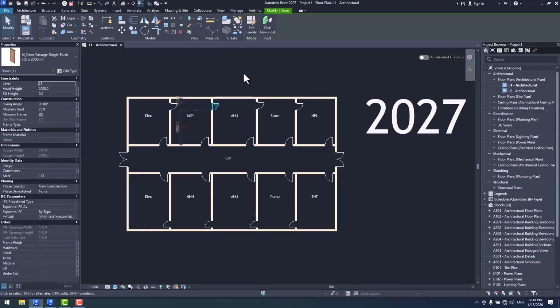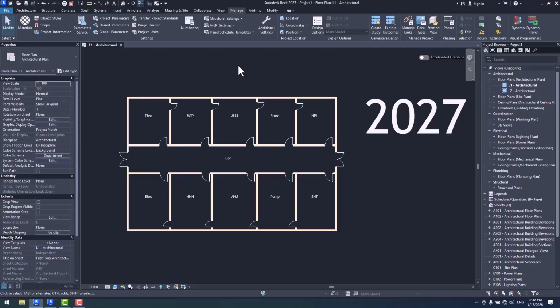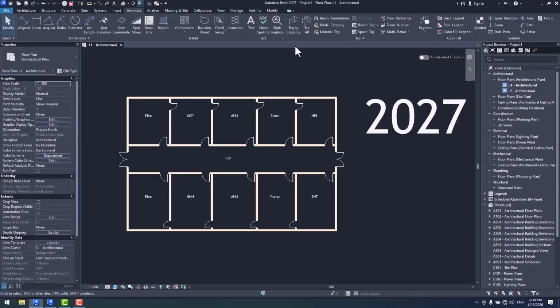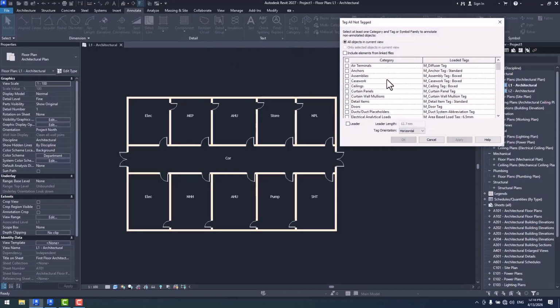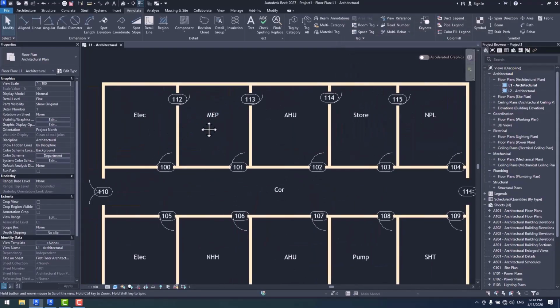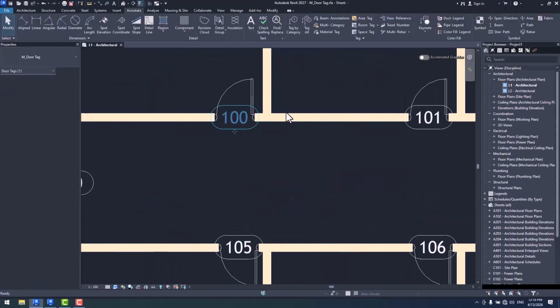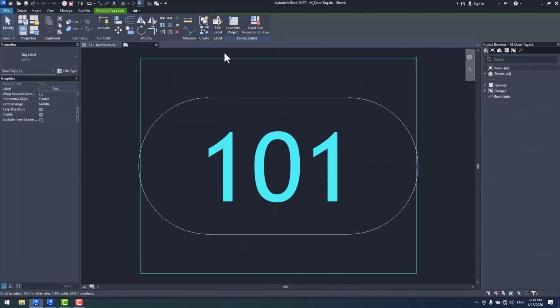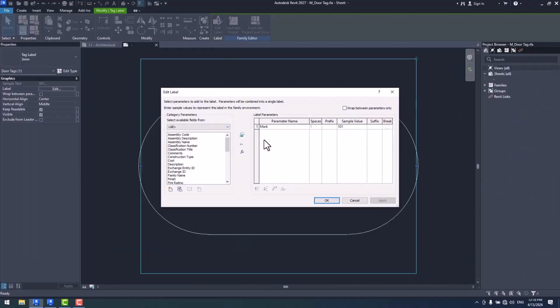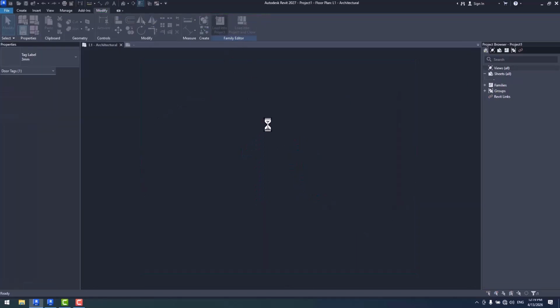First, let us set up some tags. Well, we can actually skip this. I mean, in that case, we would get the codes within mark, but I guess it's better to set up some tags first. So I'm going to use tag alt and set up these tags for doors. Now let's see what is the parameter that is being used for this tag. So then let's enter the edit family, mark. We can always change this, like give me type mark instead. Now load this back in.